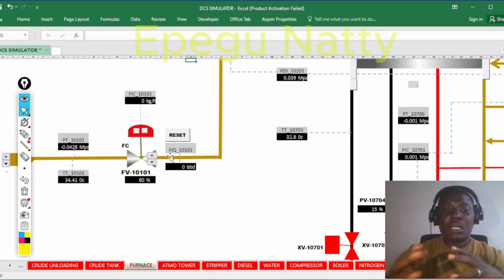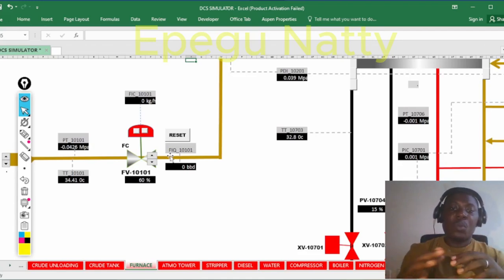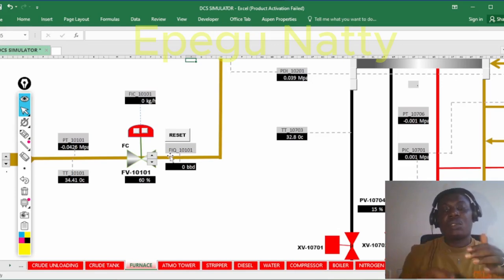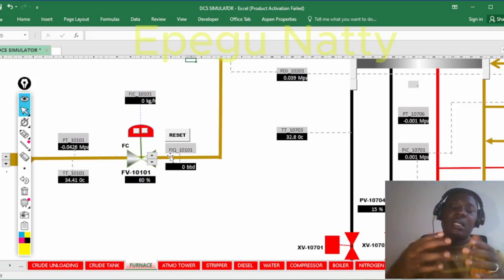When there is less resistance, the pressure is going to be reduced. But when the pump is running and there is low flow, we have a lot of resistance. That resistance will raise the pressure on the line, and this also goes for the effect of temperature too. The control valve also affects the temperature on the line, which is not good.